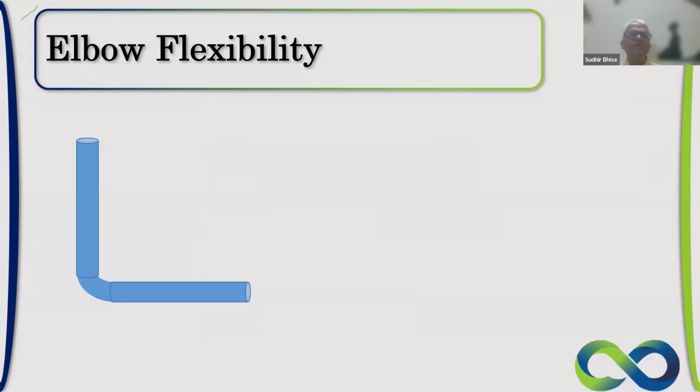So now the next component in the piping is going to be an elbow. Now elbow, what are the properties of the elbow? Bend radius, change in the flow direction, short radius and long radius. And when it is higher than 1.5D, what is the terminology that we call? The bends are, property wise, with different angles. They are 30, 45, 60, etc.